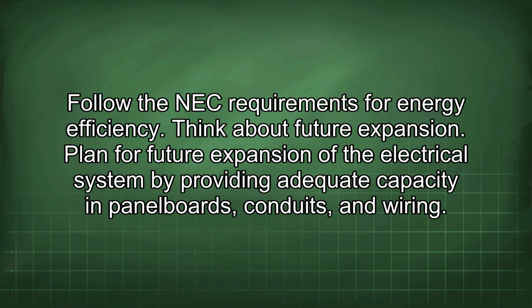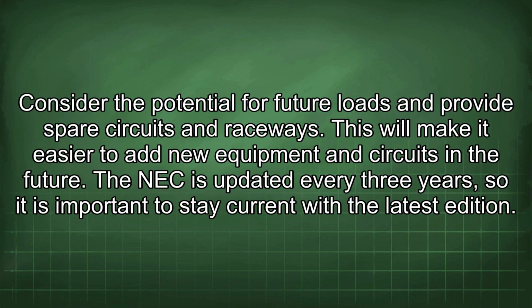Think about future expansion. Plan for future expansion of the electrical system by providing adequate capacity in panel boards, conduits, and wiring. Consider the potential for future loads and provide spare circuits and raceways. This will make it easier to add new equipment and circuits in the future.